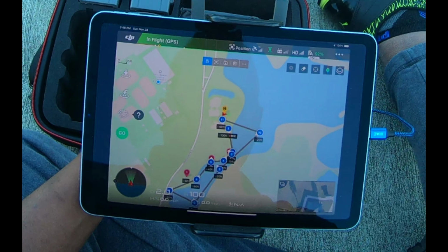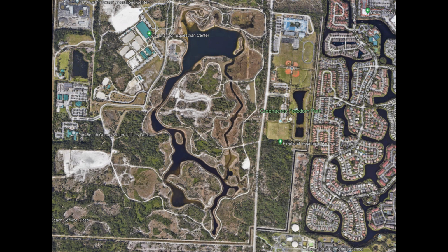Also, before you fly, study your terrain and know what obstacles you need to be looking out for. This will require visiting the site and choosing a takeoff location. Your launch point will be 0 AGL, and all vertical distances will be calculated based on your launch point. This is especially important when flying in mountainous terrain, but let's leave the mountainous terrain for later.